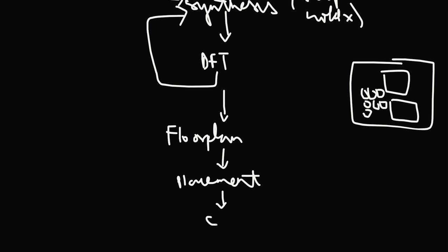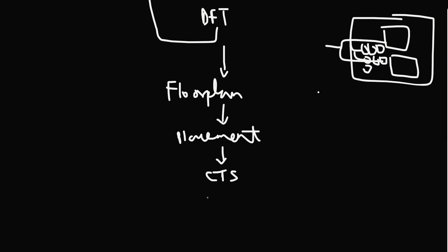And then we have the clock tree synthesis here. Clock tree synthesis is where we give the complete clock path. Before this we do not have any kind of clock to any of these logics. So here all the clocks are fanned out to all the logics within the chip. This is the stage of clock tree synthesis.